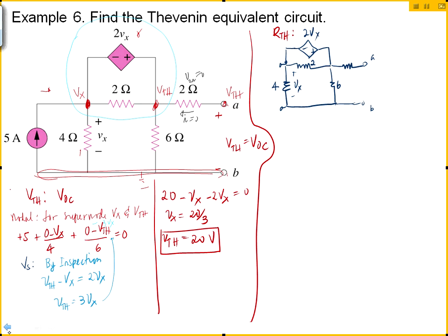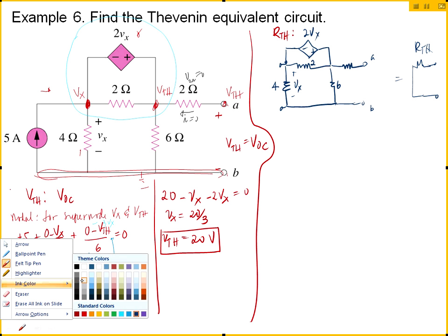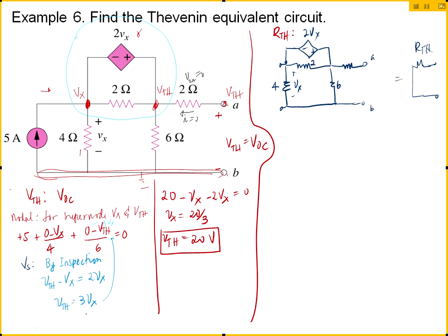So what do we do, according to what we said earlier? It says here, according to Thevenin, this is equivalent to a single resistor, R Thevenin. We don't know what R Thevenin is, but according to Mr. Thevenin, one way to find it is by applying a test voltage source in the terminals, or a test current source. Which one do you want to try? Voltage or current? You want current? Okay, let's do current.